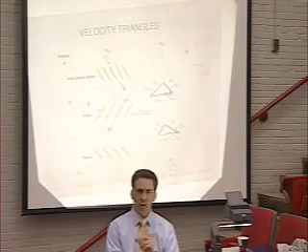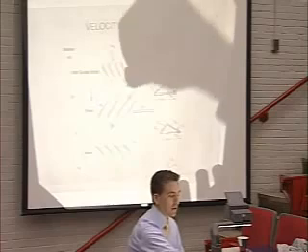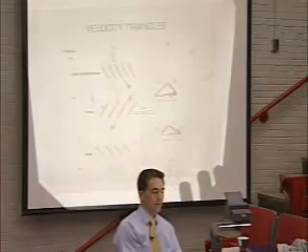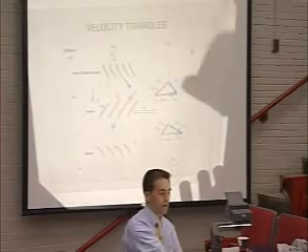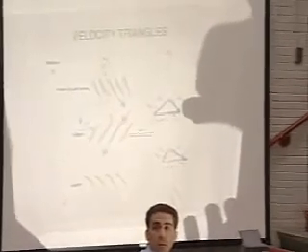Let me just go through the steps again. You assume the flow leaves the trailing edge at the trailing edge angle. So that gives you this vector. Basically, this flow is turned or added some swirl, but since it's not moving, it's not done any work. It's just converted internal energy to kinetic energy.